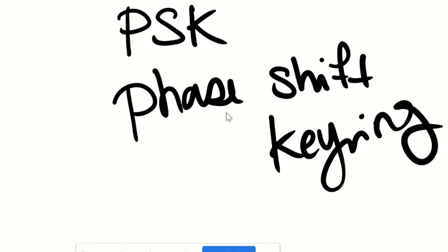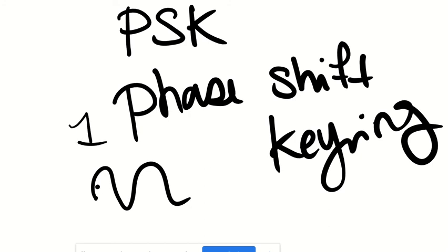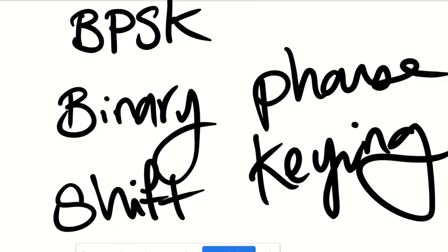For example, if somebody asks you what is phase shift keying, you at least know I'm sending 1 and 0, and I know now that I'm sending it with an analog signal, right? You know that by now. For 1, I have one phase. For 0, I have another phase. By phase I mean where the signal starts. And then, of course, they all have their own sub versions.